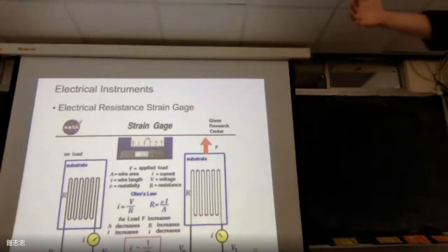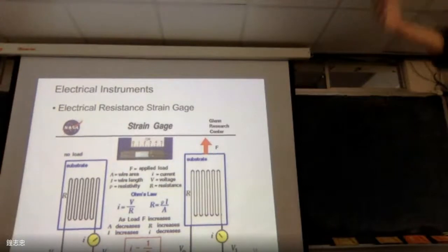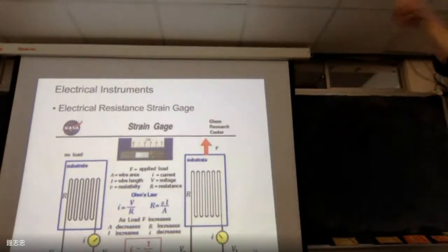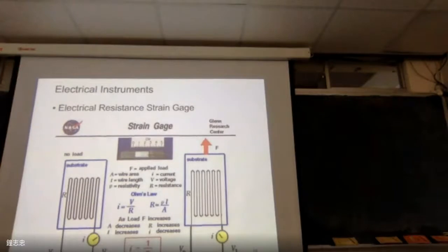So when you have a longer distance for the transmission line, especially using a strain gauge or the capacitance transducer, the level of the original signal, I mean the output one, will decrease. And along the transmission line, you may encounter noise, so the level of the noise will increase. So it means that the SNR will decrease, right? So this is not so good for the measurement.